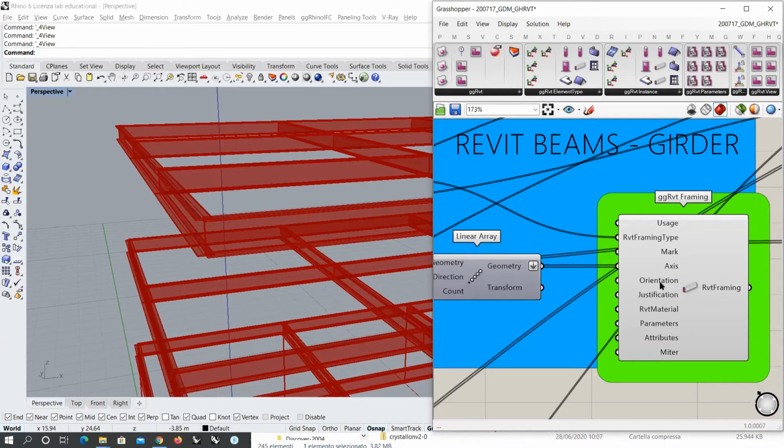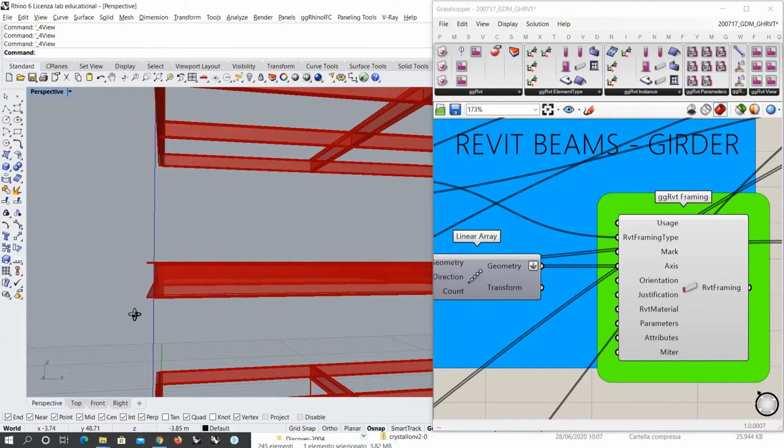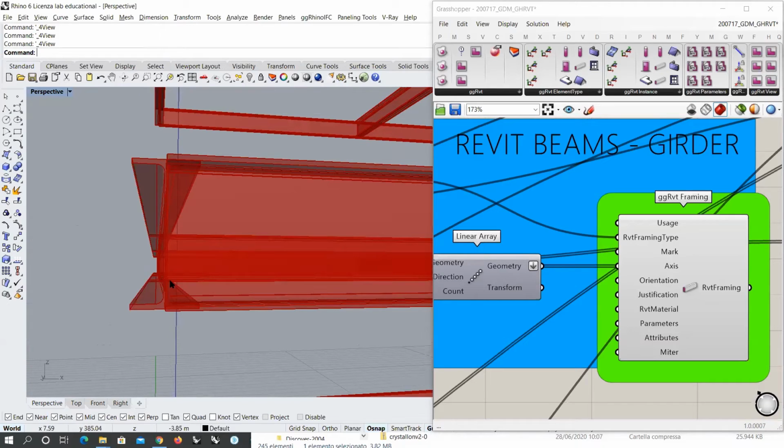Now, normally you don't need to orient a cross section, the cross section for a beam. It would be something like having an IPE beam like this, and eventually pretending to reorient its cross section in order for this cross section to lie like this. But if you do something like this, you are basically compromising the efficiency and the performance of this beam, of course. So as regards beams, unless you have very, very specific needs, it's something that you might not want to take into account.